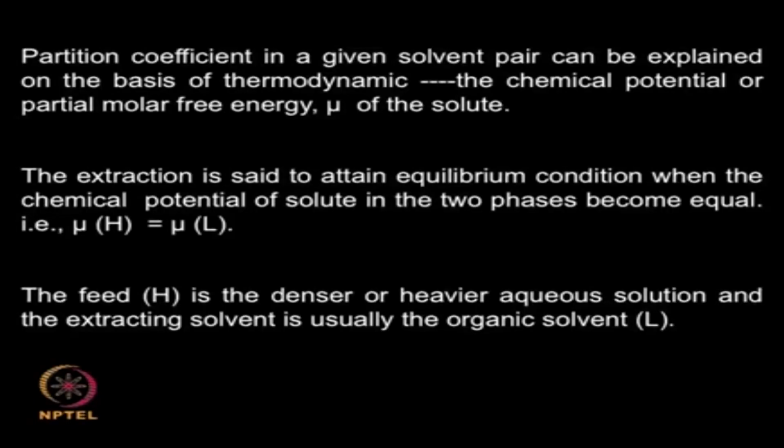That is an ideal condition, but sometimes we do not give enough time for the solute to partition effectively and reach equilibrium. If the viscosities are very large, then the movement of the solute molecules from the heavy phase to the light phase takes a longer time, but I might not wait for such a long time, so they actually do not reach equilibrium. But for design or calculation purposes, we can assume that the chemical potentials of the streams leaving the extractor reach equilibrium, that means they are equal.